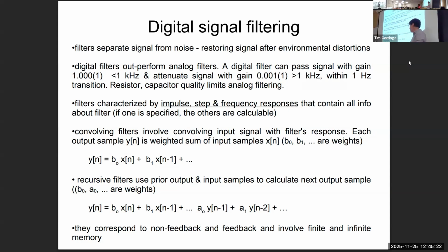And in a recursive filter, not only does the output depend on the input values, the current one and the prior one, but it depends on the prior output value and the output values before that. So that's what I'm writing down here.